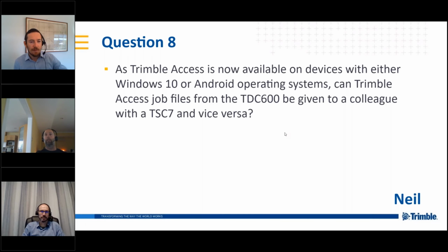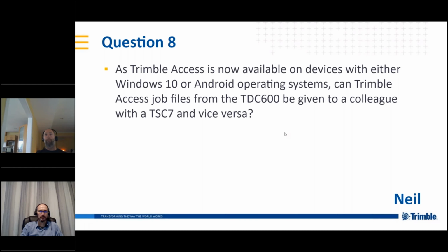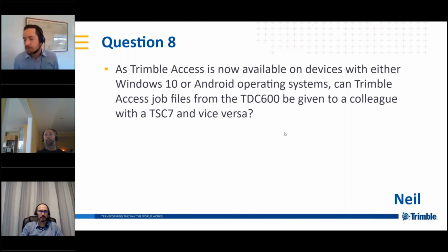This is an excellent question, and I think more companies will start exploring the smaller Android device. Currently we only support this one model, but who knows what will be supported in the future. Yes, you can transfer a job file from the Android TDC 600 to the TSC 7 on Windows 10 and vice versa. Remember that Android support has only just come out in Trimble Access 2020, so the other controller you're sending to would need to be at least that version.